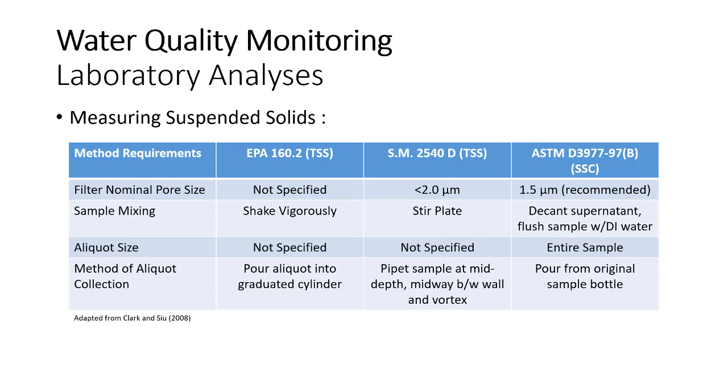They compared the three different sediment methods that are really commonly used. We've got the EPA method, the standard method, and then the new one, which, as I said, is the one the USGS uses, the SSD. It's an ASTM method. It's kind of interesting to compare the different specifications for how to actually do it. In terms of the idea, it's really the same. You've got your sample, and you're trying to get the solids out of that sample in some way and measure the amount of solids in it. You can think about it generally in the same way, but the way you technically do that is different between those three methods.